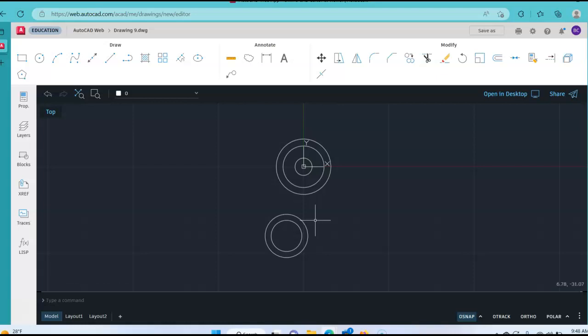The last thing that I need to do here is put those 30 millimeter radiuses on. So I've got an arc that kind of comes from here to here, and an arc that comes from here to there. Now let's just talk about this arc tool. The problem with using the arc tool right now is we really don't know exactly where it comes in. Well, we do kind of. So we've got the tangent object snap done. So I'm going to go to the tangent there for the first one, and the tangent.